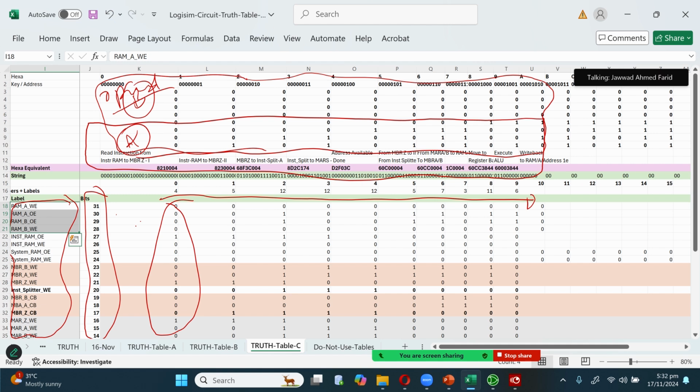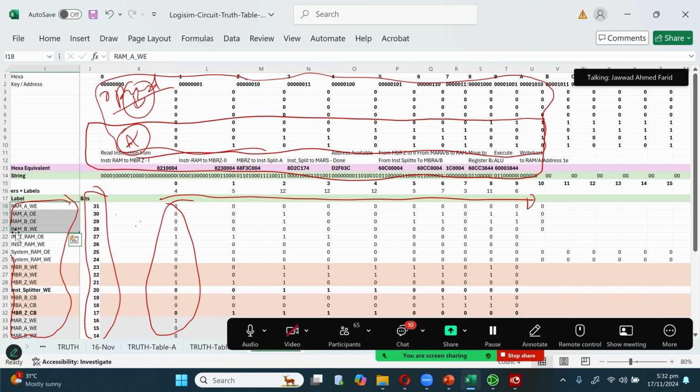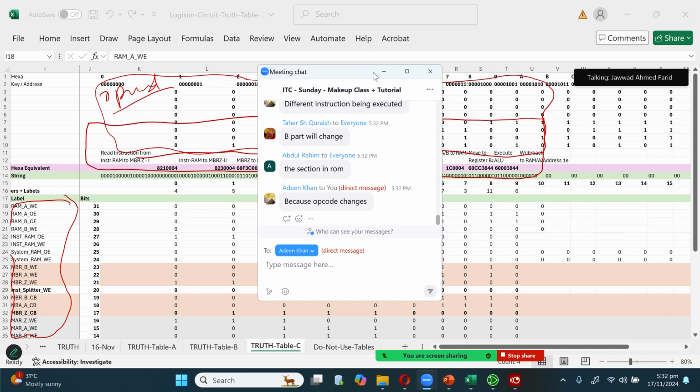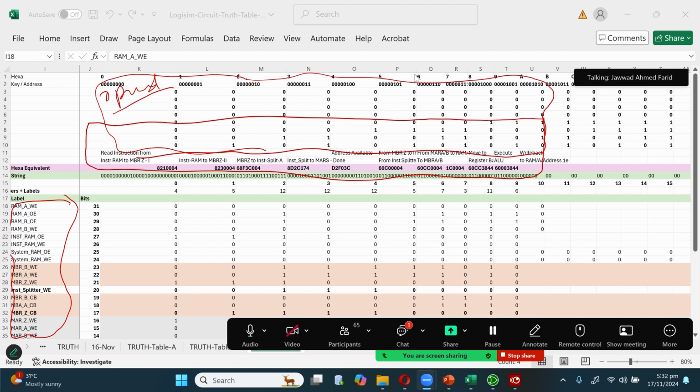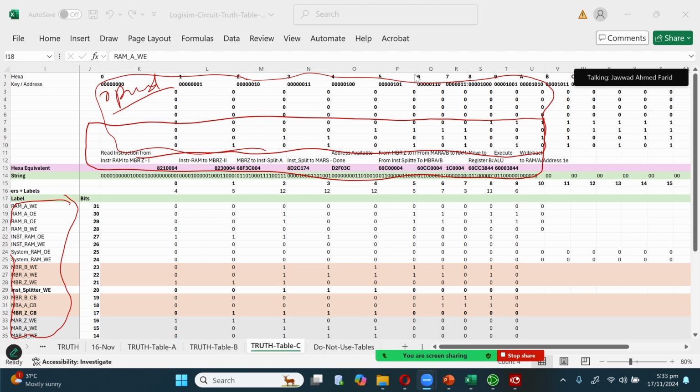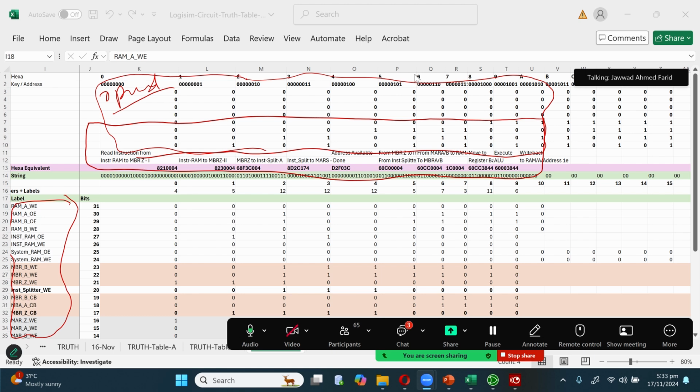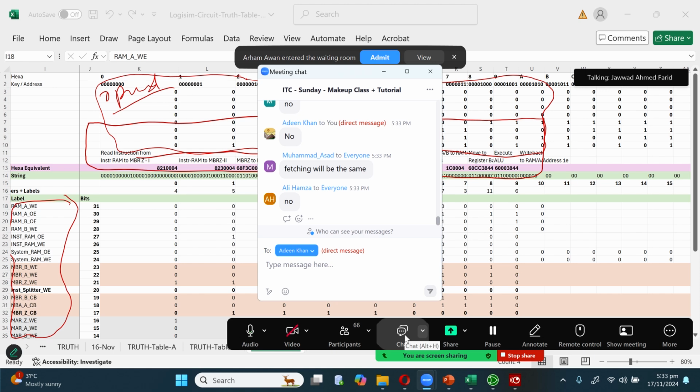So let's say this is a simple load instruction. This says, load memory test, and the opcode is 000. And let's say the opcode for add is 001. So what will change? What do you need to change to make it work for add? So you have to remember, for most operations, the key part, the common part, the basic part is the same. The basic part is what? Fetch data. Is that going to change from operation to operation? Will that be different from add, subtract, multiply? It'll be the same, right? So fetch will remain the same. Okay, so now what will change?